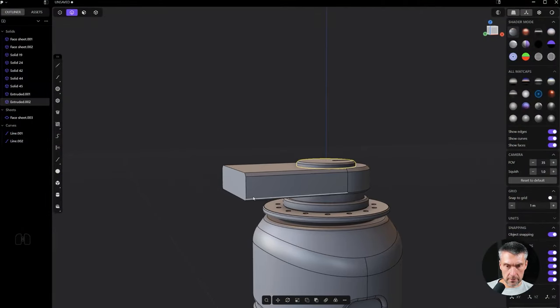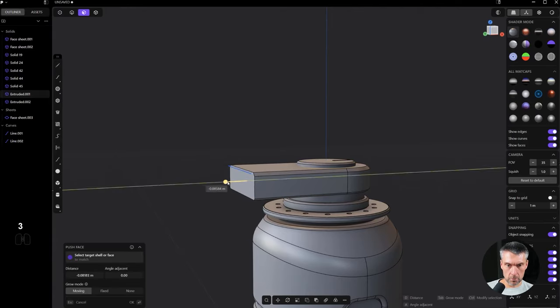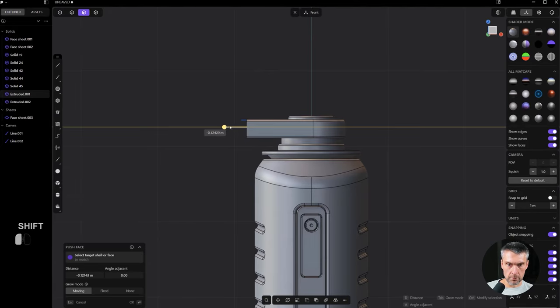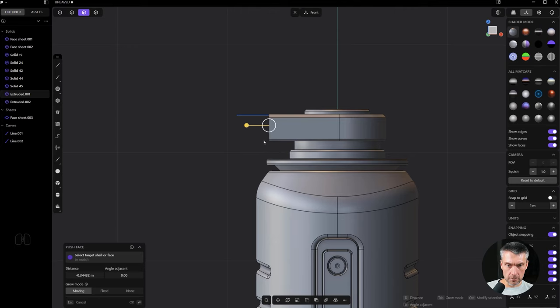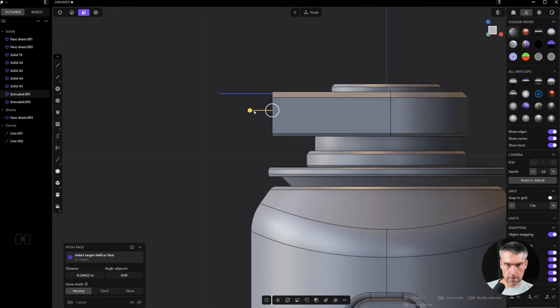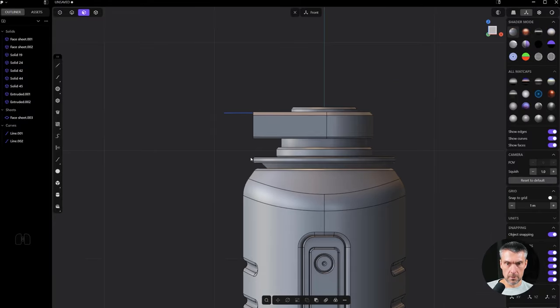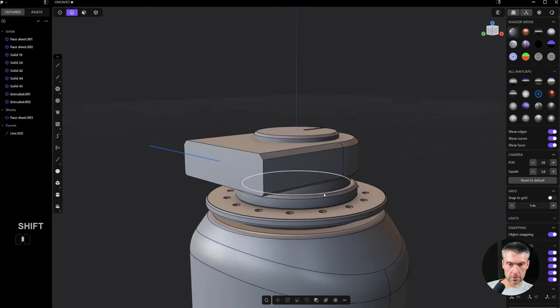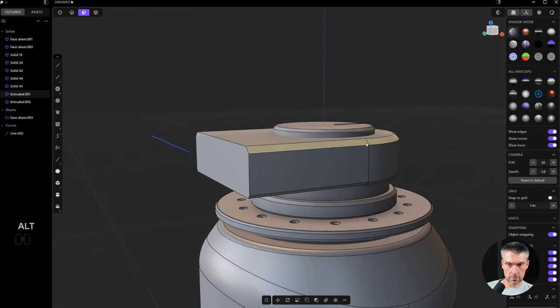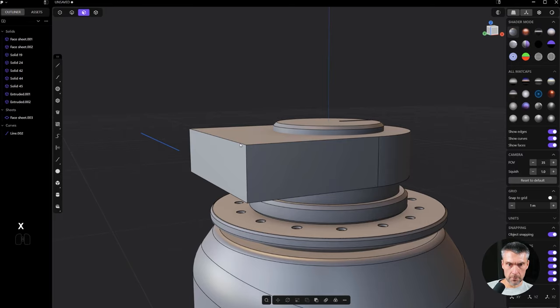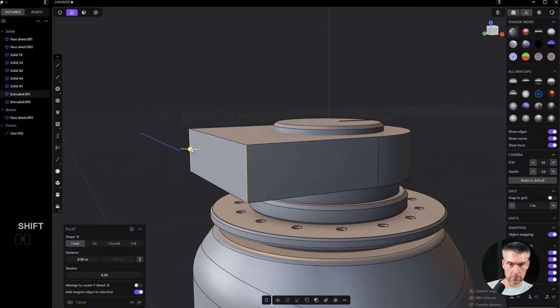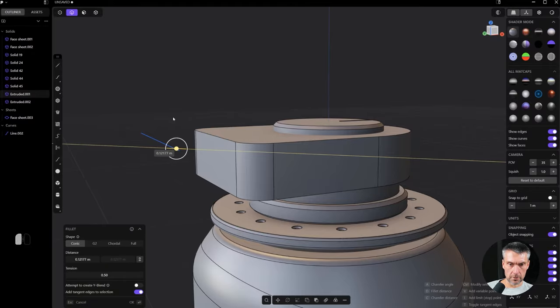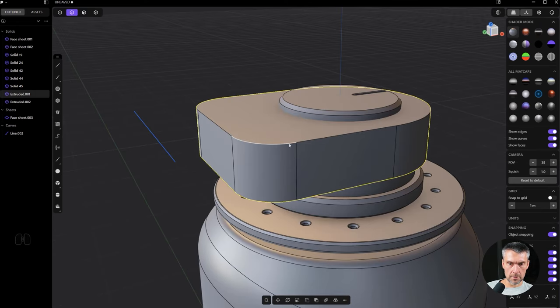That works. And now here in the back, we need to figure out this mechanism for releasing the pin and all that. This could be a similar distance here, more or less. That will work. Now in this situation, I'm going to grab these two chamfers and nuke them. And before I do anything, I'm going to bevel this here. And then I'm going to chamfer. And same here.